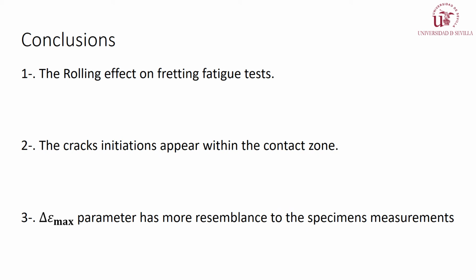The first conclusion is that the fretting fatigue bridge produces an effect of rolling on the contact path, which increases the contact zones, and this changes the stress and strain field. The second conclusion is that the crack initiation does not appear at the contact edge as the theory states, but within the contact zone, as you could see through the experimental measurements, and this was verified by the finite element method analysis.